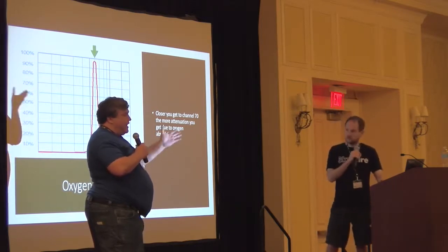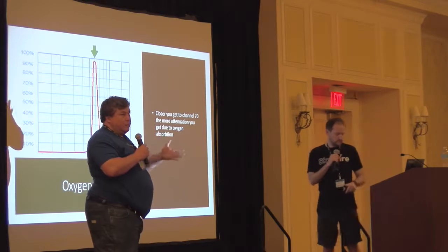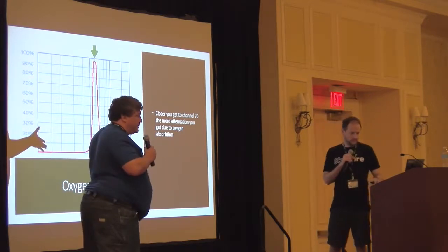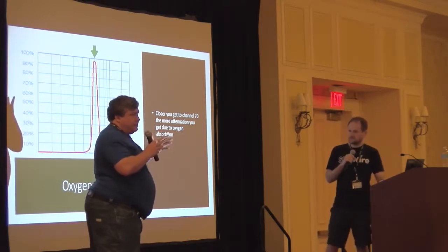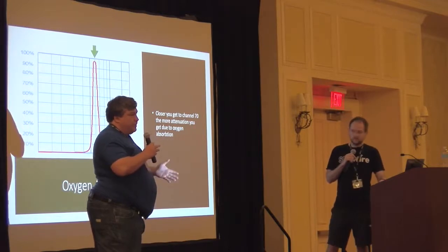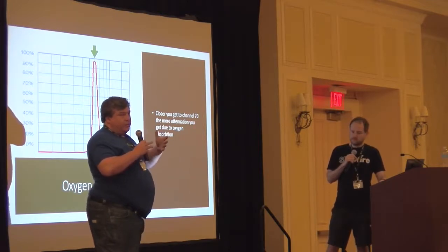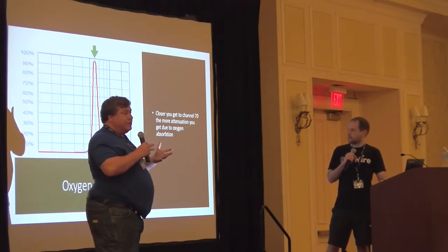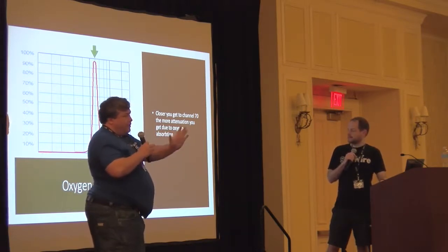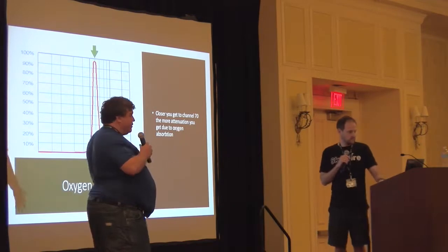You're getting away from the oxygen absorption of the 60 gig, because there's a tuning frequency where the oxygen kind of overtakes the signal. So the further away you get from that, the better your signal is.